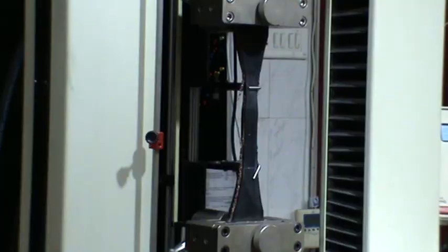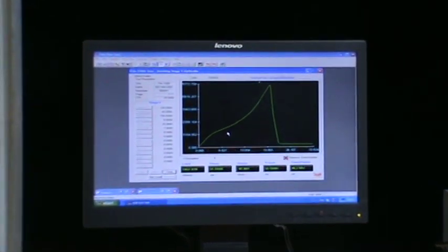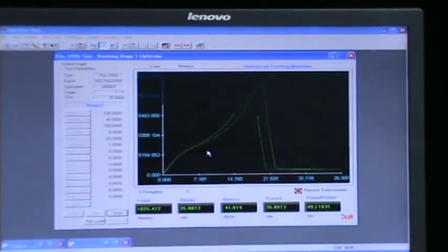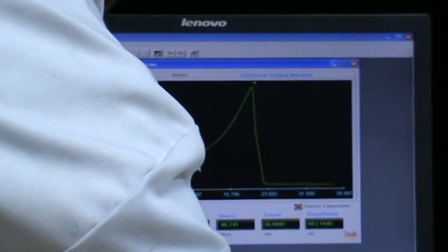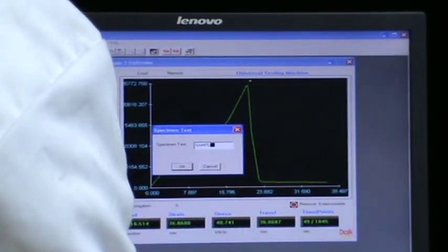If a belt is manufactured poorly, not all plies may be evenly tensioned, and therefore the total belt strength could drop significantly below the combined strength of all the plies. This test is therefore a good indicator of belt quality.